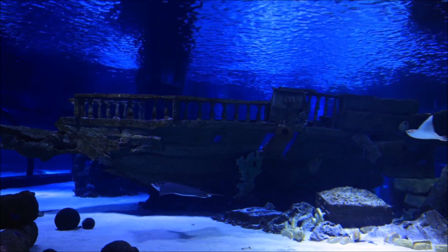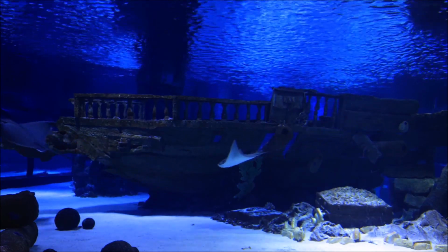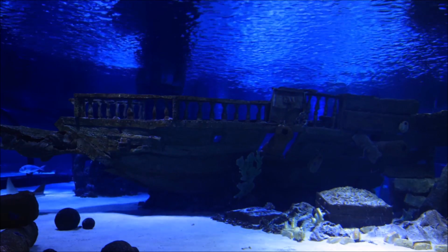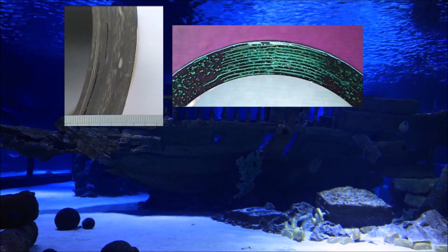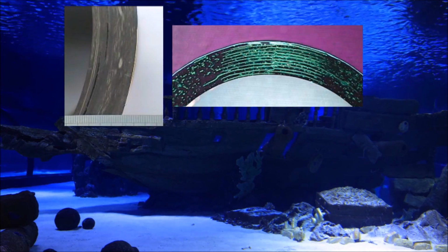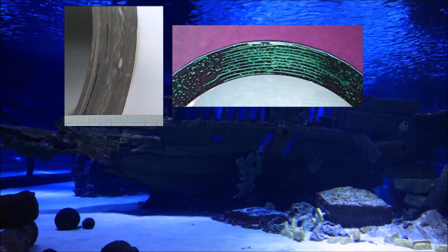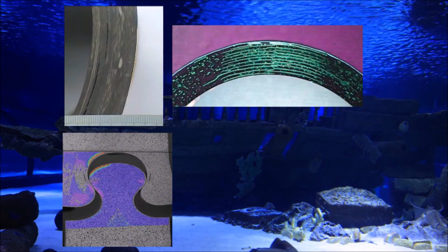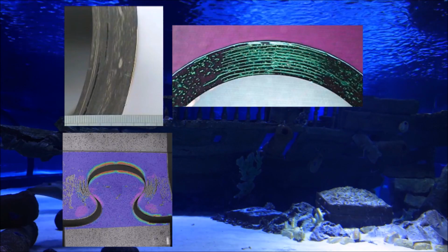The influence of such defects on implosion pressure depends not only on the overall dimensions of the defect but also on its shape and its position within the wall thickness. For example, a delamination near the outer surface may not affect implosion pressure, while the same defect near the internal surfaces can buckle and initiate premature failure, as you see in this video as well. So you see internal delaminations. This makes the prediction of the effect of even geometrically simple defects quite complex.